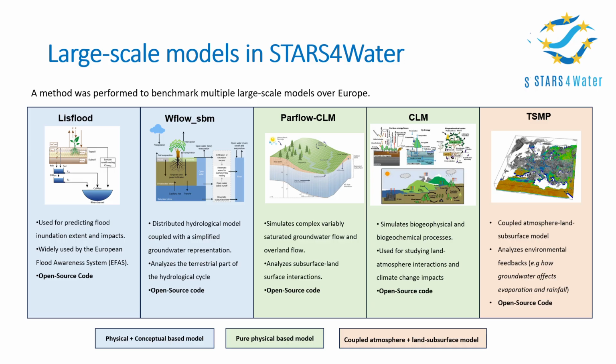In the Star4Water project, we worked with a set of open source models. For example, the LISFLOOD model is an operational implementation for flood forecasting, and it is the core model used by the European Flood Awareness System. The Wflow SBM is a distributed hydrological model that is coupled with a simplified groundwater representation, and it's excellent for analyzing the terrestrial part of the hydrological cycle. The ParFlow-CLM is ideal for simulating complex, variably saturated groundwater flow and overland flow.